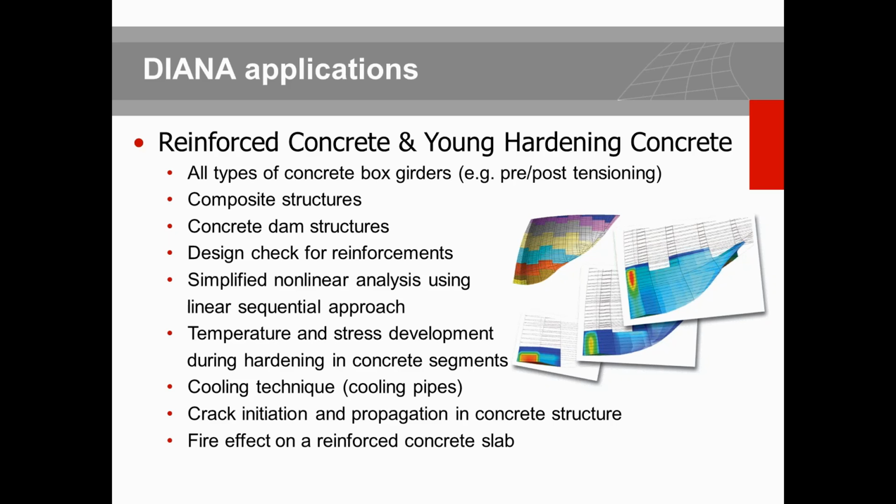Design check for reinforcement, also based on the model code that we offer, to check that the amount of reinforcement complies with the requirements from the model code, and that the amount of crack that is occurring in the model is also in line with the limitations that the model code offers. Simplified nonlinear analysis is also one of the strengths that we offer in DIANA for the practical engineers who do not want to enter into a deep nonlinear setup of the model. So what does that mean?